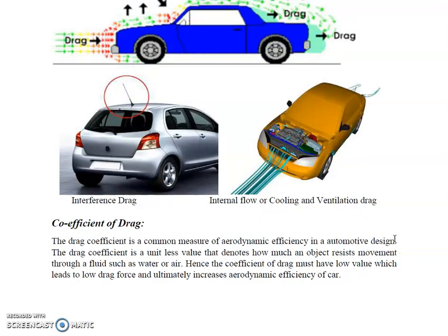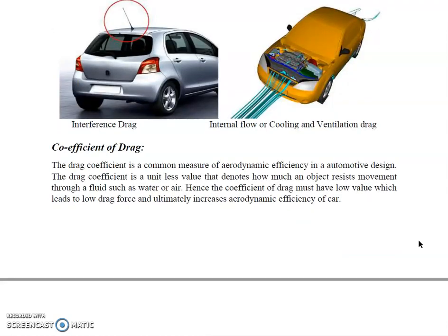Now next we'll discuss the coefficient of drag. The drag coefficient is a common measure of aerodynamic efficiency in automotive design. The drag coefficient is a unitless value that denotes how much an object resists movement through a fluid such as water or air. Hence, the coefficient of drag must have a low value, which leads to low drag force and ultimately increases the aerodynamic efficiency of the car.